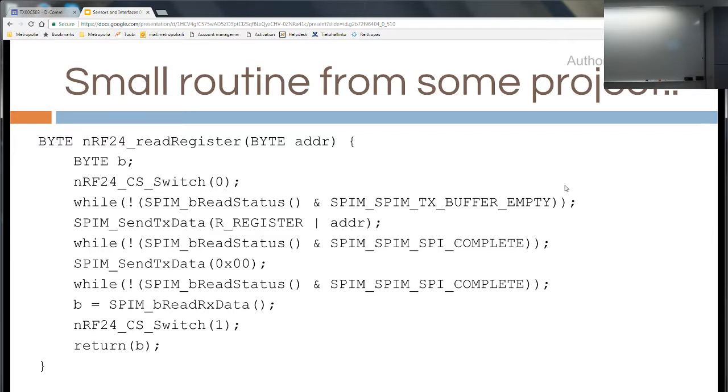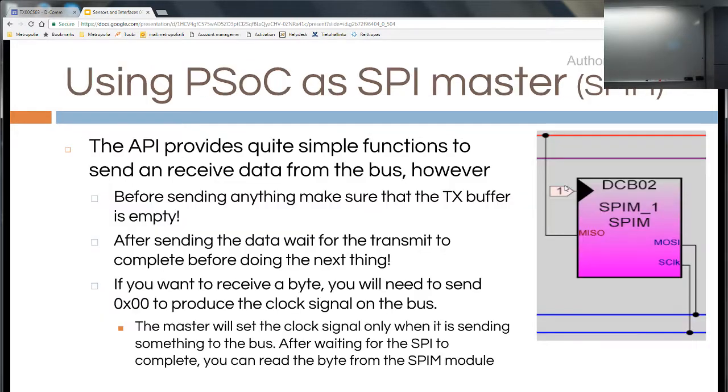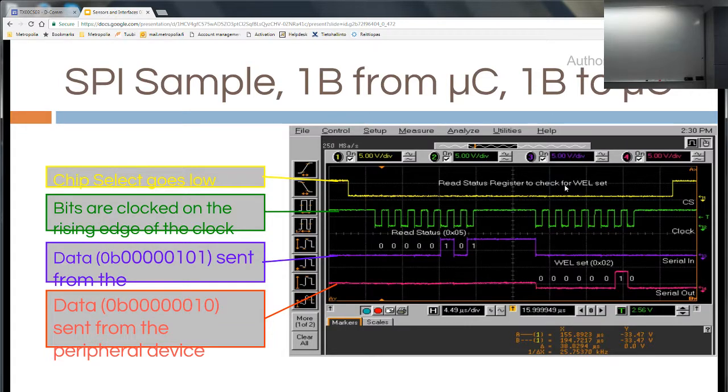This is the command, and the answer to that command is the status register, but that's not the one we would be reading. The next byte, while we are sending the zeros, actually would give this register, like in here. So this could have been the first byte setting the command to the device, and then the next byte with the dummy output.